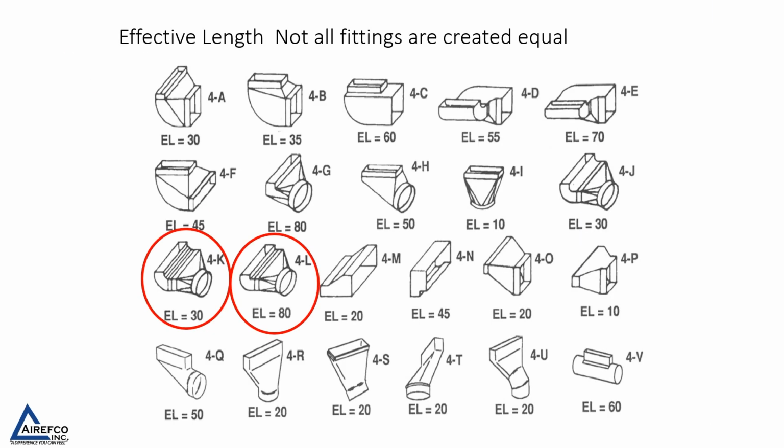So if you're designing ductwork, or if you're a technician working on a problem job, always consider your ductwork and your fittings and your equivalent length, and try to keep your static pressure as low as you possibly can.